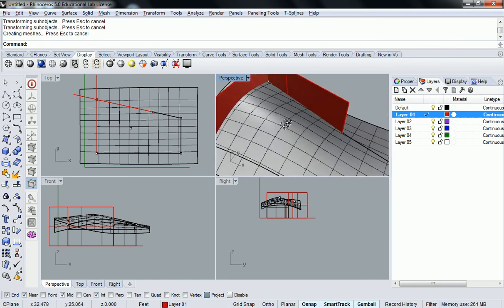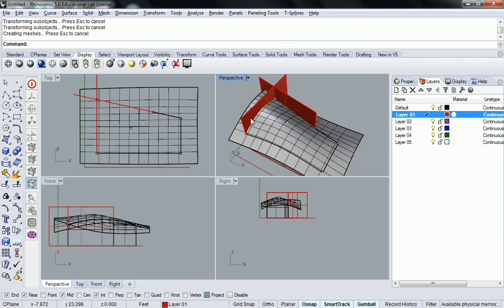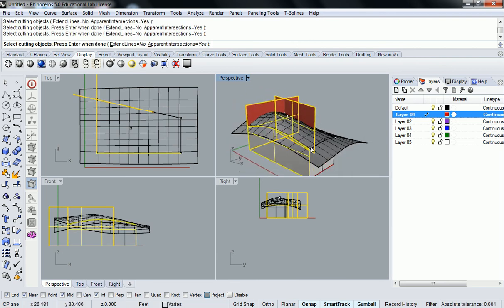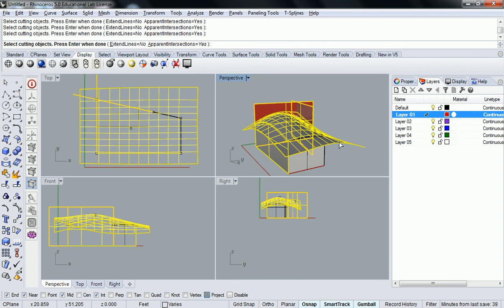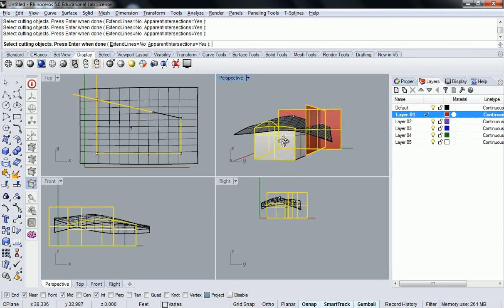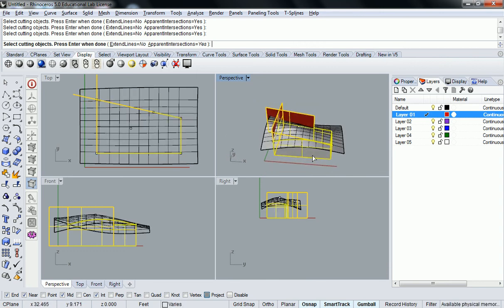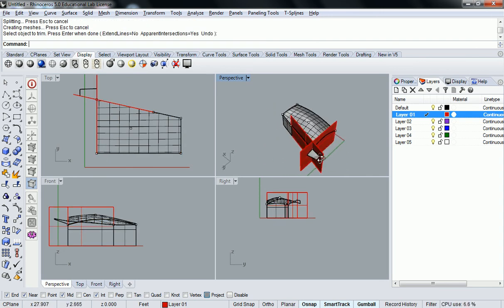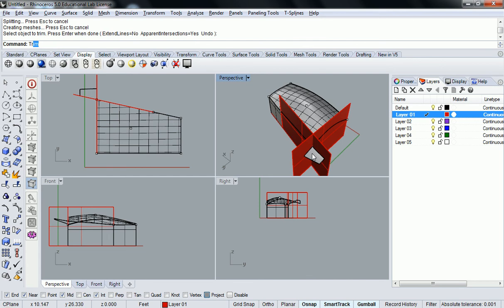So I basically just recreated the original profile off of that. And so then you can select all of your exterior walls like this, or I'll do the trim thing. Select your exterior walls like this, and because they all intersect, you'll be able to trim off the exterior face. Oh, got an extra corner there.